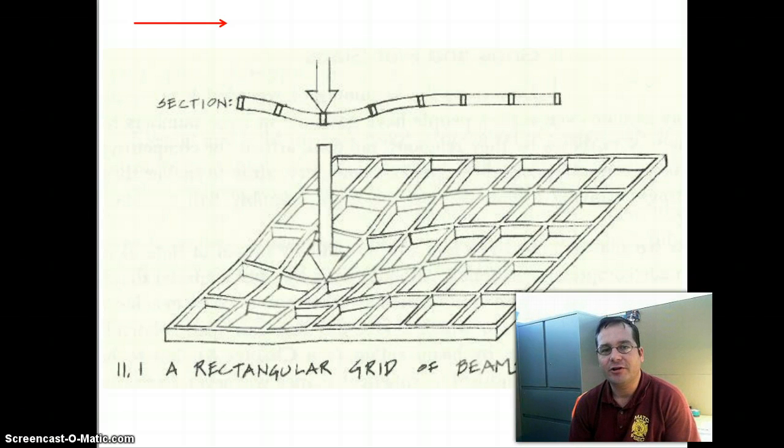This is structurally challenging because you're trying to create an open space with no intermediate supports. You can imagine a basketball court with a column running up through the center to support the roof would be dysfunctional, and so assembly occupancies tend to be structurally challenging. Now, in antiquity, almost all of our building materials were strong in compression and weak in tension. So again, they would display that property we call anisotropy, where they are anisotropic. They are strong in one direction and weak in another.